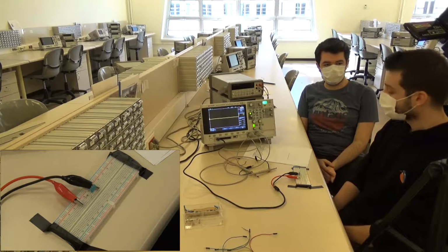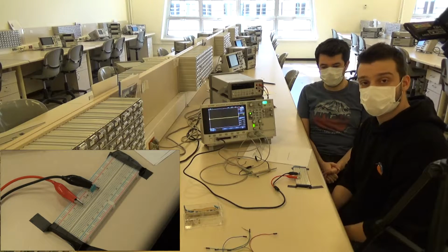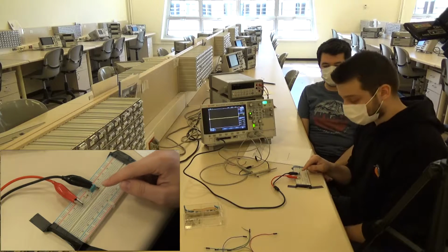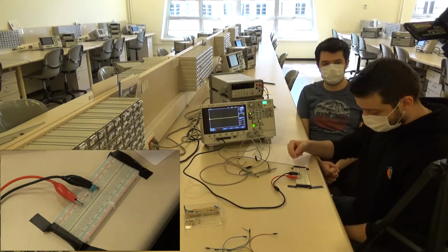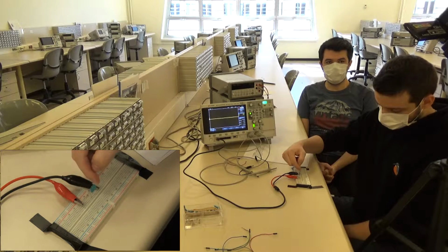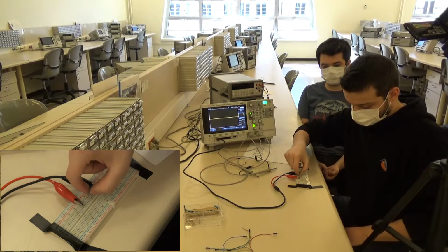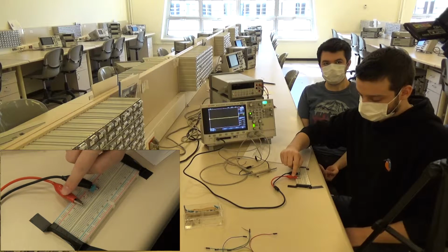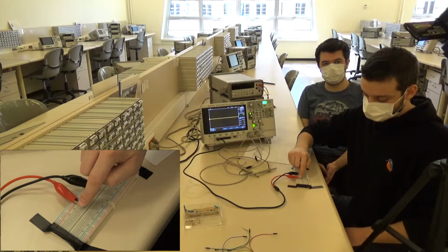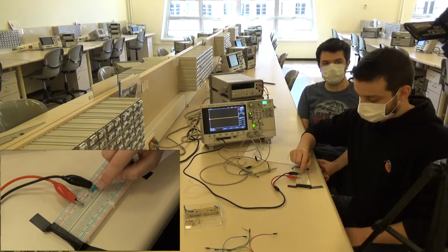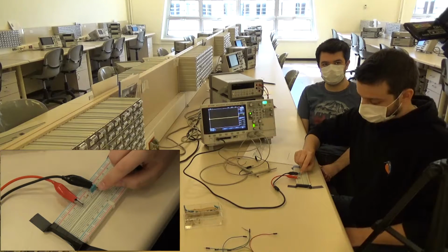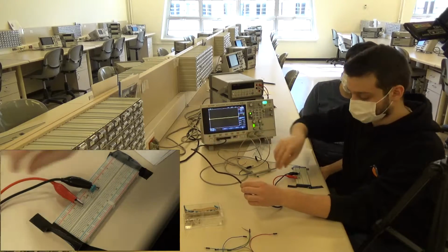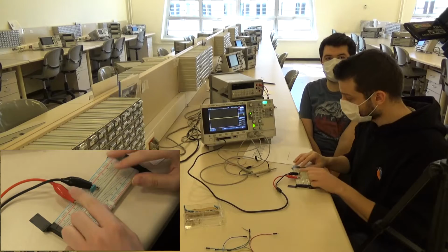Okay, you can start. I will build an RC circuit today. I have a 10 kilo ohm resistor and a 10 nanofarad capacitor, and I've connected them like this. They're connected in here, and I'm applying the positive side of the function generator to the resistor's leg and the negative side of the function generator to the capacitor's leg. As you can see, this cable is the input to our circuit right now.